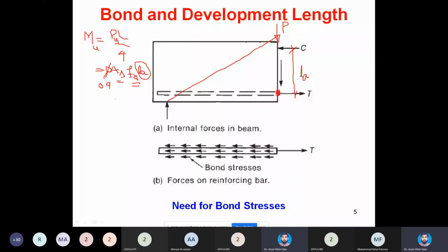So in this way, this area of steel which I provided in this beam is based on the condition that T will be equal to C. And this T will be AsFy. And further, the strain in the steel will be 0.005 or bigger when concrete will get 0.003. So the strain diagram is also known. I know that it should be 0.005, and concrete over here will crush finally.